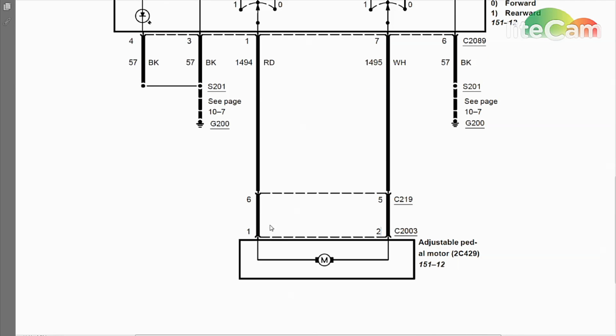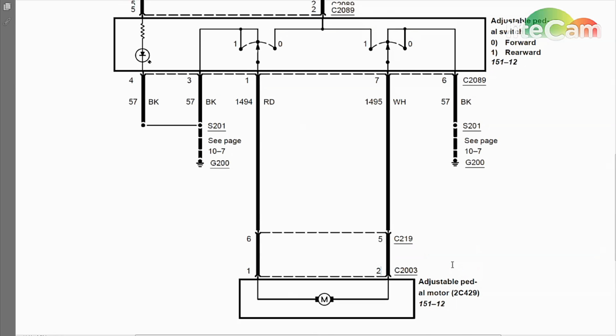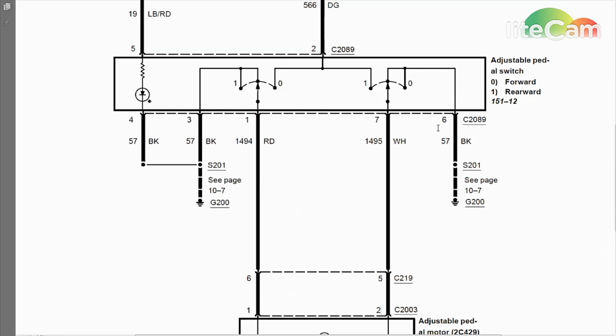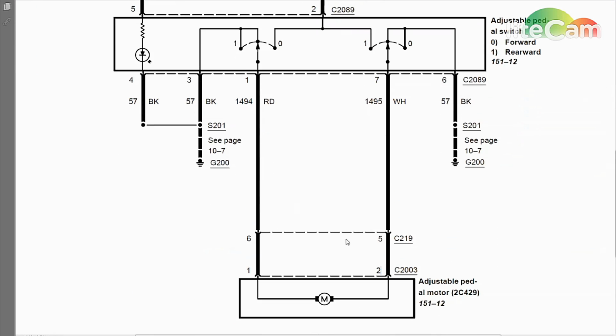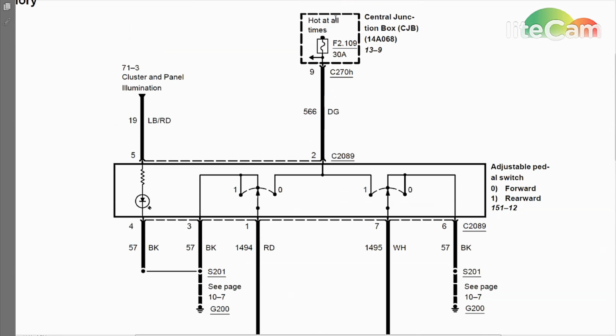Now all the ones I've ever had to diagnose or change out a component on has been, unfortunately, the motor itself. The motor and the cables and all that down there, all part of one unit, so it's kind of expensive, but this is the part that actually failed down in there. The switches never have problems, never seen no circuit problems, and depending on how bad this is down here, the fuse almost never blows on them either.